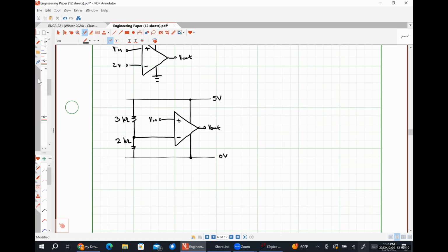But Vx is still going to wind up being negative 30 because it's the opposite polarity. It's the same voltage, but opposite polarity. Yeah, so it should be a positive 30 volts there after doing the source transformation. Because if the head of the arrow is on the right, the positive sign is on the right. The tail of the arrow is on the left, or negative is on the left. It's a positive 30 there.